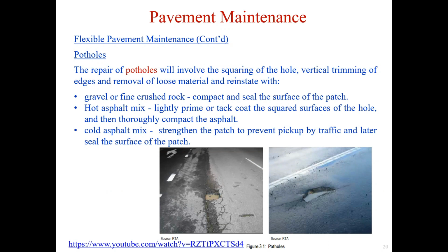Potholes are usually due to a cracked bituminous surface, allowing moisture to enter the pavement. The pavement may soften slightly, or water may penetrate horizontally under the bituminous surface. In either case, a small area of the cracked surface is likely to lift out under the action of the traffic, starting a pothole. Such potholes usually appear after rain.